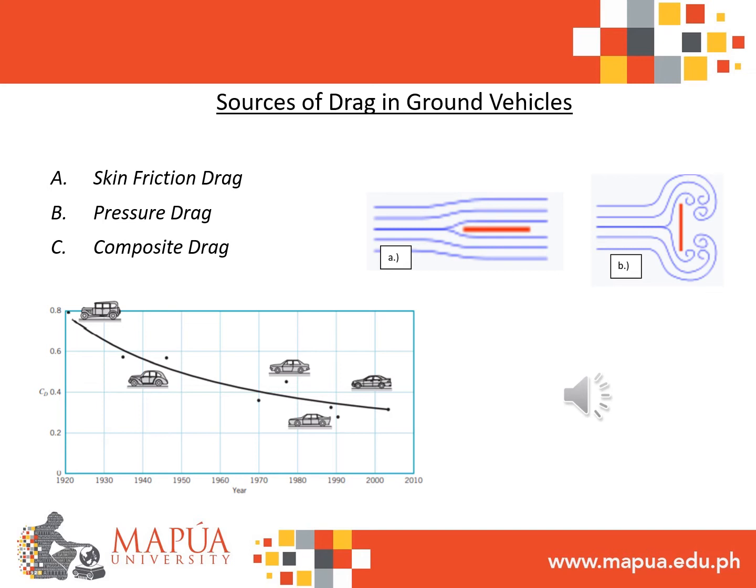If the surface of the object is perpendicular to the flow, the shear force that will be induced will amount to zero. The shear stress induced by the fluid is also related to its viscosity. Viscosity is defined as shear stress required to produce a unit rate of shear strain. Since most of the common fluids have small viscosity, this drag is almost negligible since its amount is so small.